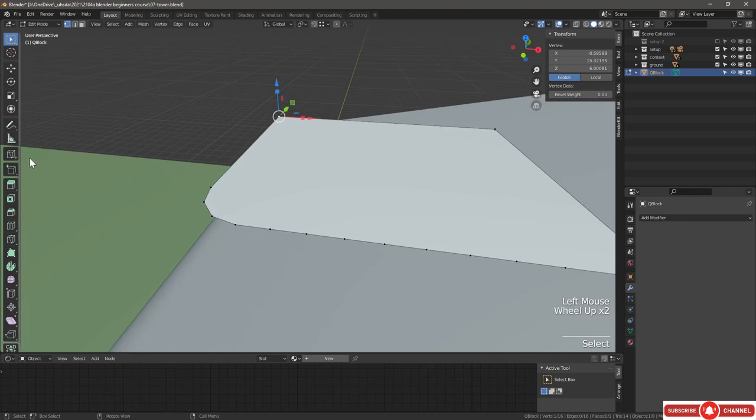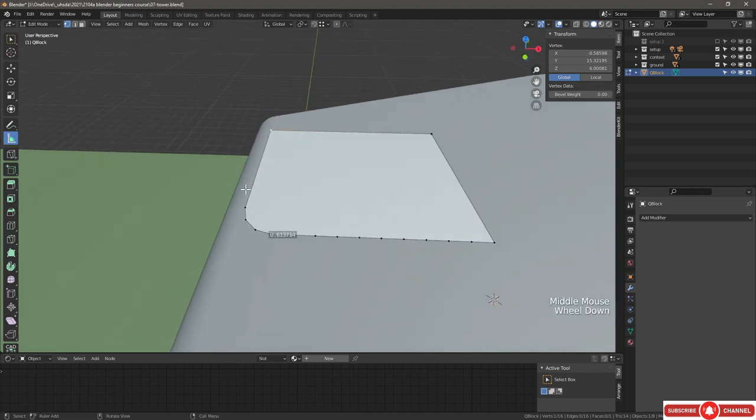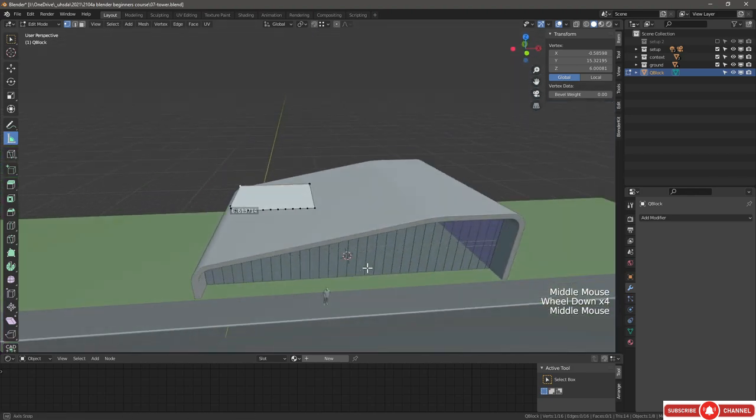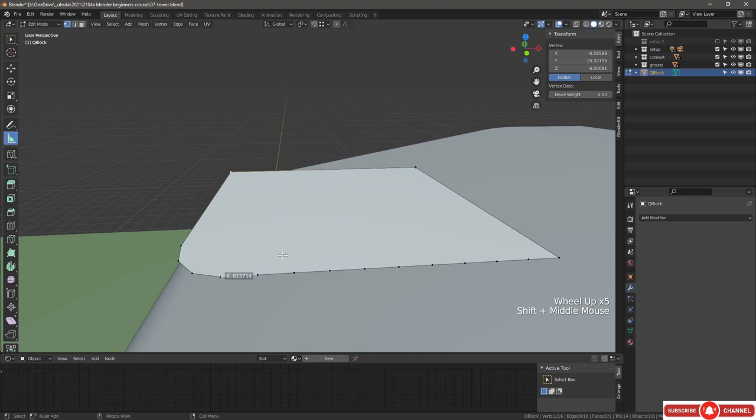So we can measure the precise distance with the measure tool. If I click on it, hold Control, and we can see that's 600 mil. So we can go smaller, but that's quite a good size for a window. Curtain walls at storefronts and at ground levels, they do tend to have bigger pieces, whereas up higher, the scale is different. So we want to respect that more intimate scale.